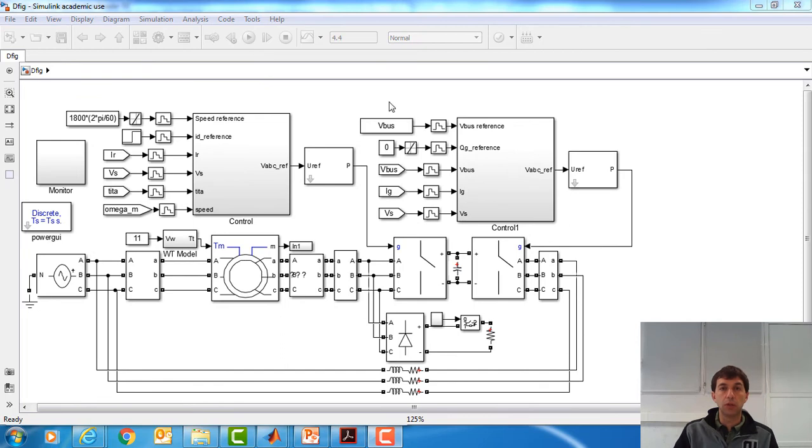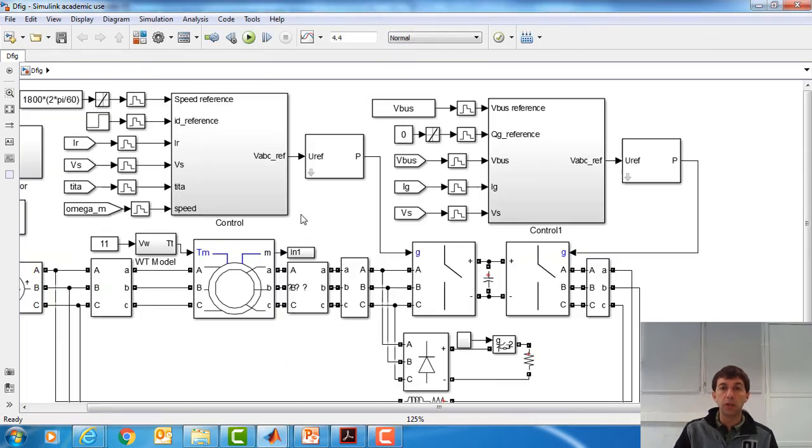the simulation, but before doing it, there is one important thing missing. When the crowbar is activated, the rotor and grid side converter must be protected, so the current shouldn't go through this way. All the current, all the energy should be burned in the protection.